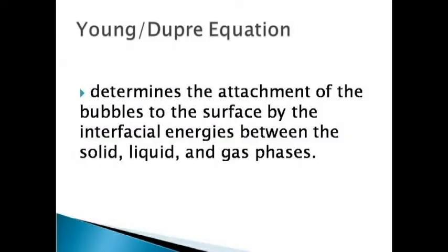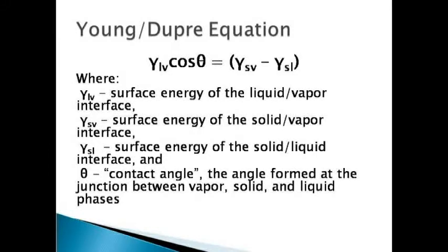Attachment of the bubbles to the surface is determined by the interfacial energies between the solid, liquid, and gas phases. This is determined by the Young-Dupré equation. Young-Dupré equation: surface energy of the liquid-vapor interface times cosine theta, or the contact angle, equals surface energy of the solid-vapor interface minus surface energy of the solid-liquid interface.